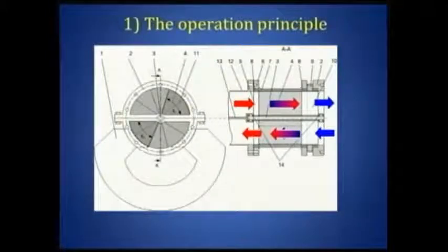For these people who don't know how magnetic refrigeration operates, I have here a little picture which shows very nicely the principle. You see underneath, on the left, a magnet. This creates a magnetic field in the lower part, and in there we have a porous cylinder turning, like, probably you know, rotative heat exchangers in air conditioning. So we can flow through with a fluid through the lower part, and with another fluid through the upper part, half circle, and we have a part which is not in the magnetic field.